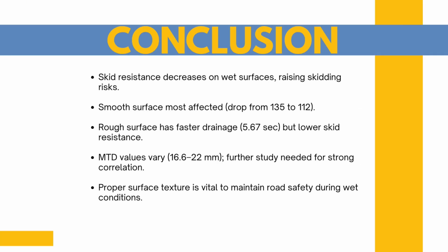In conclusion, skid resistance decreases on wet surfaces, increasing the risk of skidding. The smooth surface was most affected, dropping from 135 to 112, while the rough surface drained water fastest at 5.67 seconds. It showed the lowest skid resistance.